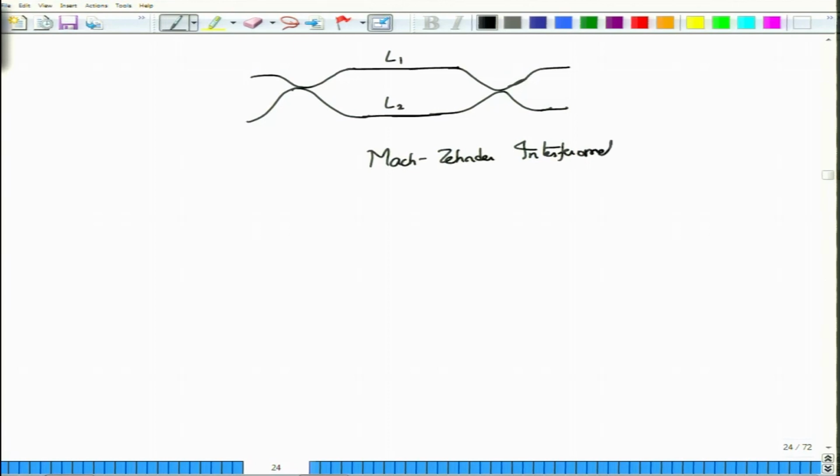If you are looking at these interferometers, one way to construct a fiber based Mach-Zehnder interferometer is to do this. So you have Ei1 here, Ei2, and then you have EO3 prime and then EO4 prime, just to indicate that these are intermediate signals, and after propagating each of these terms will have a phase shift, e power j phi 1, and for EO4 prime, e power j phi 2.